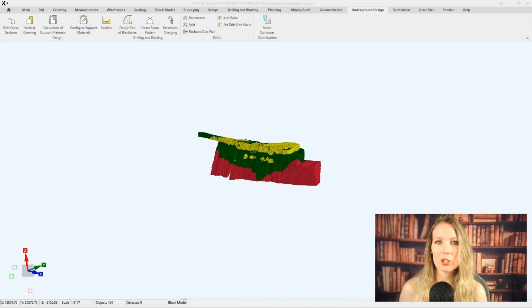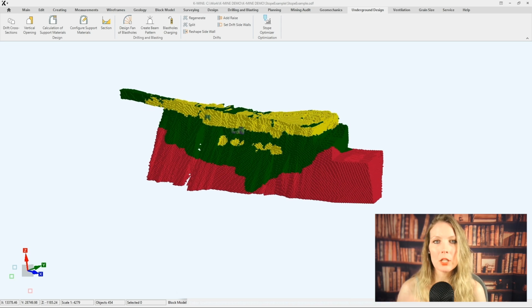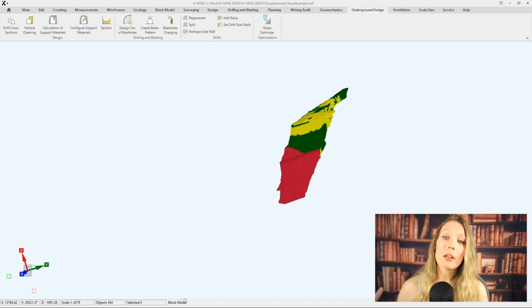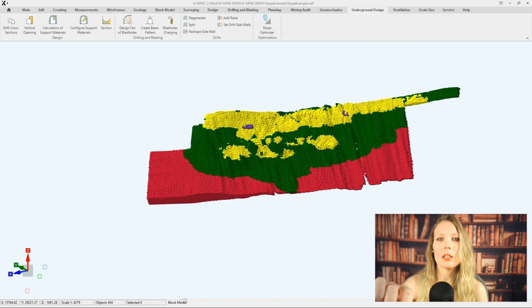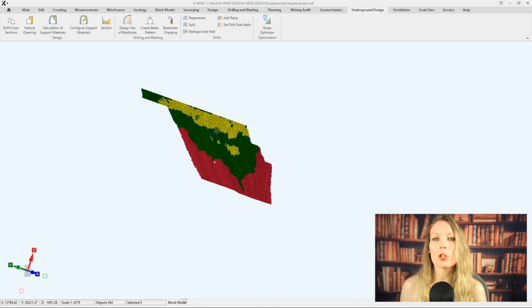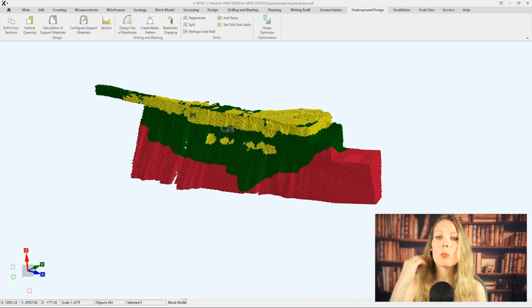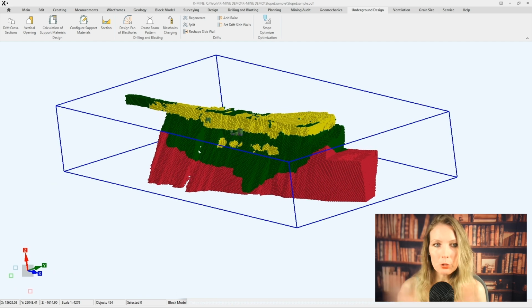To address these challenges, modern mining software solutions streamline the process of stope optimization, transforming raw geological and economic data into practical mining plans. Using KMine stope optimization as an example, we will demonstrate how sophisticated algorithms and structured workflows simplify stope boundary optimization, ensuring the most profitable and technically feasible outcomes. So how do we begin? Nothing new. We begin with data preparation and input parameters.